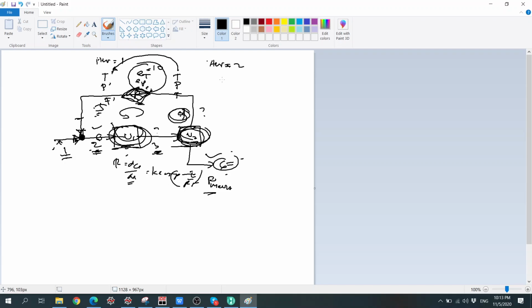Because in the plants also, not all streams have flow meters, not all streams have temperature or pressure measurements. So in doing this mass balance, we can at least have a feeling, or a better view of the stream conditions. If there is heat leakage, like we are losing heat somewhere, those kinds of things we can evaluate from the mass balance.